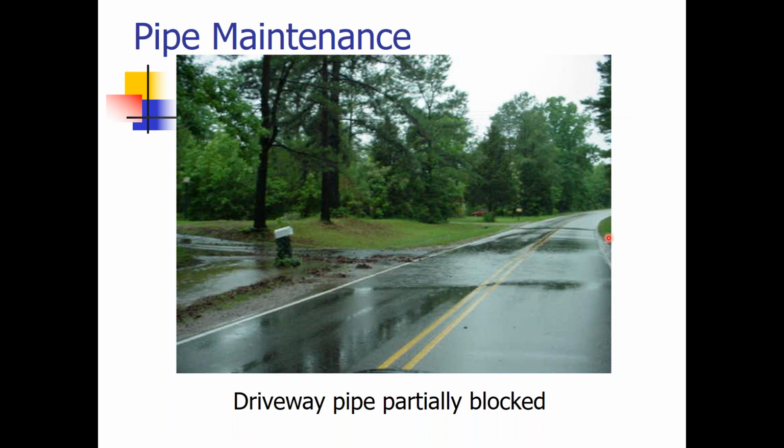You can see that we need to pull back some of these shoulders so that the water will flow properly. And notice it's not just right here. There are water flowing issues up that road as well. So what we have here is just one symptom of a problem on this roadway.